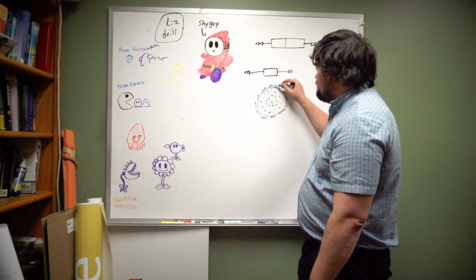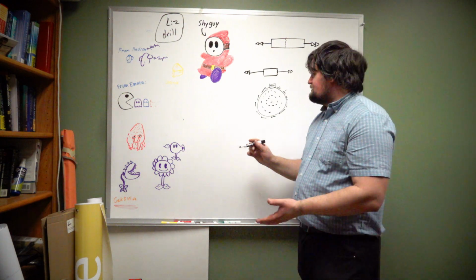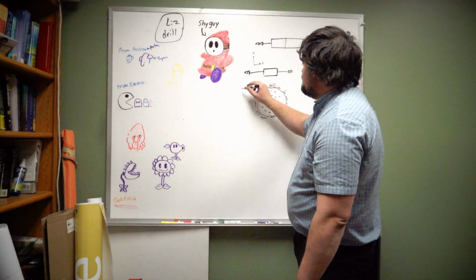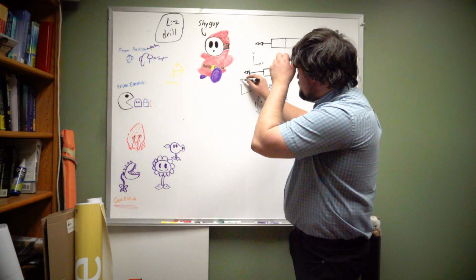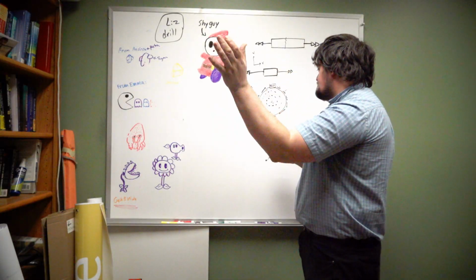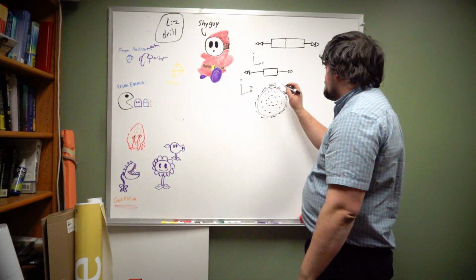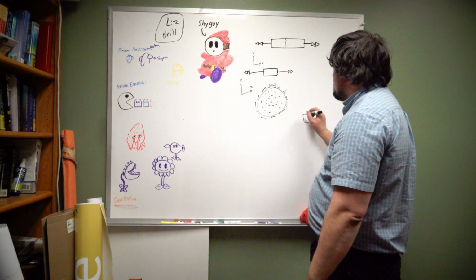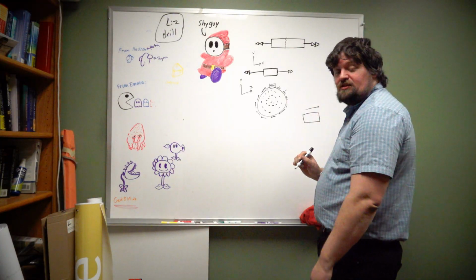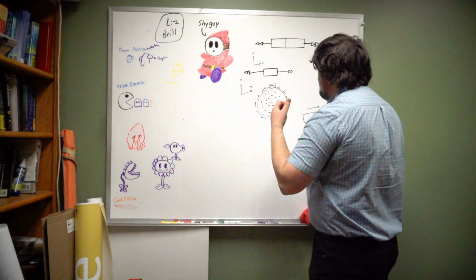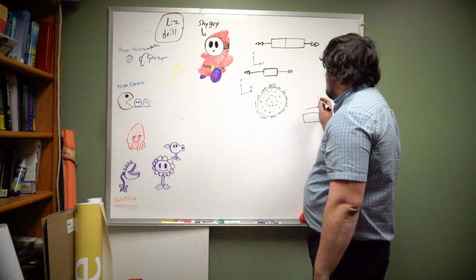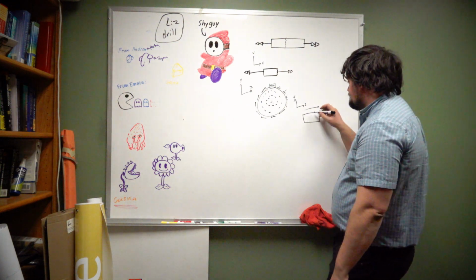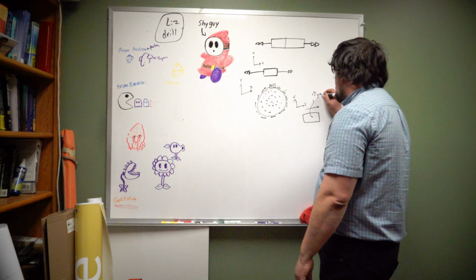Now, when we're trying to figure out what is the actual axis for this, let's go ahead and say this is the XY axis. Let's go ahead and say then that this would be the YZ axis. We'll say Z is going this direction. Okay, so if we pull out just this element, we have this curved element here. We'll call it a unit cube. We know we have a net load up here on the top of this item. This net load is acting in the Z direction on the Y face. So since that's the case, this is a tau YZ.